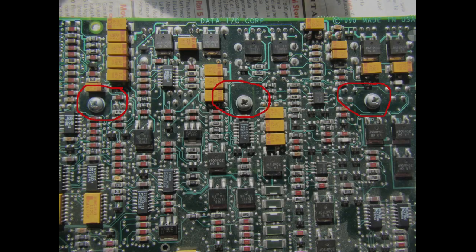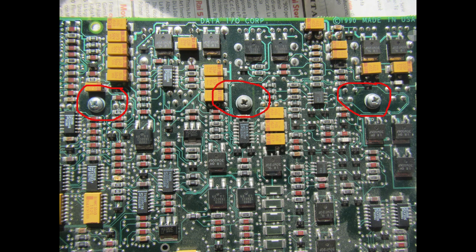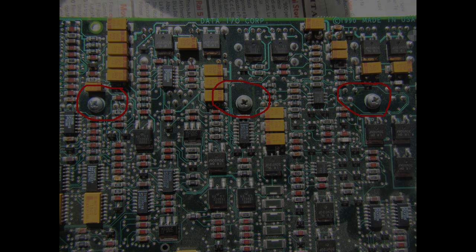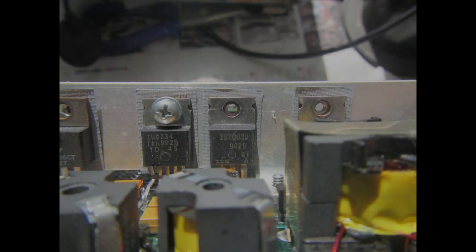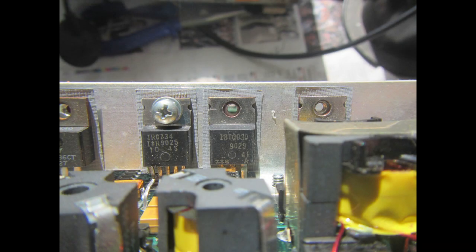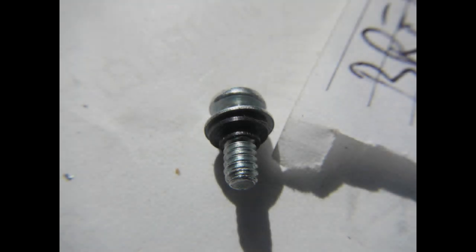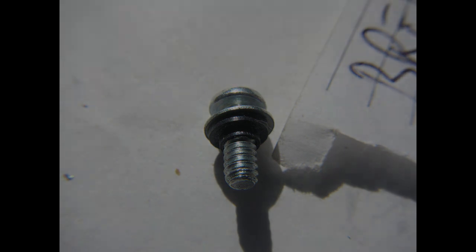So I must remove the heatsink before having enough clearance to safely substitute this capacitor. The heatsink is secured to the PCB with these 3 screws that must be removed. Then each power component screw must be removed also, and we need to pay attention to the insulating pads, avoiding damaging or misplacing them. Also, each of the screws has a plastic spacer to prevent the contact between the screws and the component metallic tab, and we don't want to lose any of those spacers.